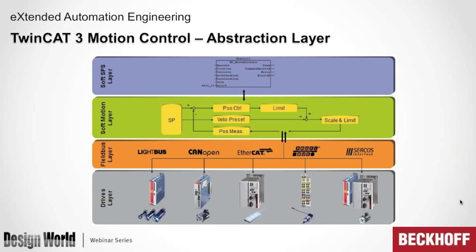In our case, for the motion controller, now we have a motion controller that says, okay, here are your scalings. I'm getting back 2,000 pulses per revolution. It takes care of all those details for you. By the time you get to programming, you are completely abstracted from having to worry about anything. I say move 10 things, and based on how I've set the system up, it's going to move 10 inches or 10 meters or 10 degrees. But I'm abstracted from having to worry about it.